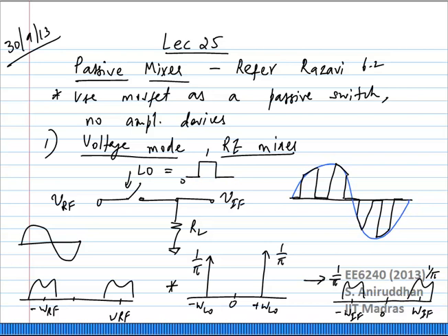Apart from that, you're absolutely right. You will see a sinc kind of shaping of these impulses. Since we are looking only at the fundamental, we are seeing this. In the case of the sampling mixer, we are going to do the math in a lot more detail in a few minutes, so we'll understand exactly how it behaves. Because this is a much simpler example, I just decided to look at the fundamental and move on.